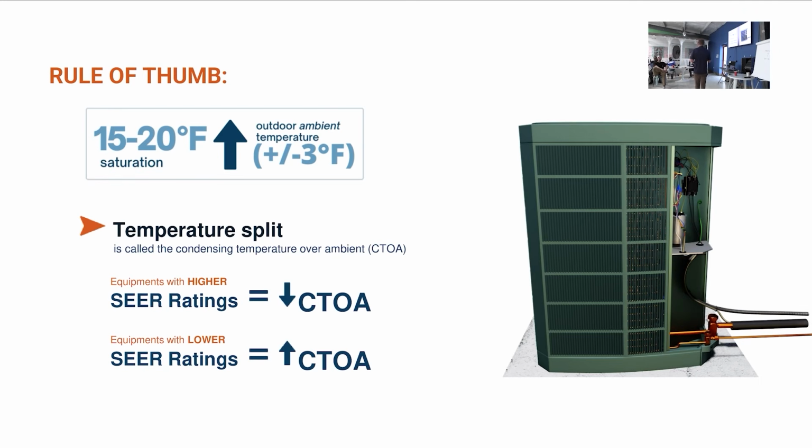Yeah, 85, so 100 to 105, right? Did I say that right? Yes, 100 to 105. You see how bad I am at math. That's what our condensing temperature is going to be on a not super high efficiency system.